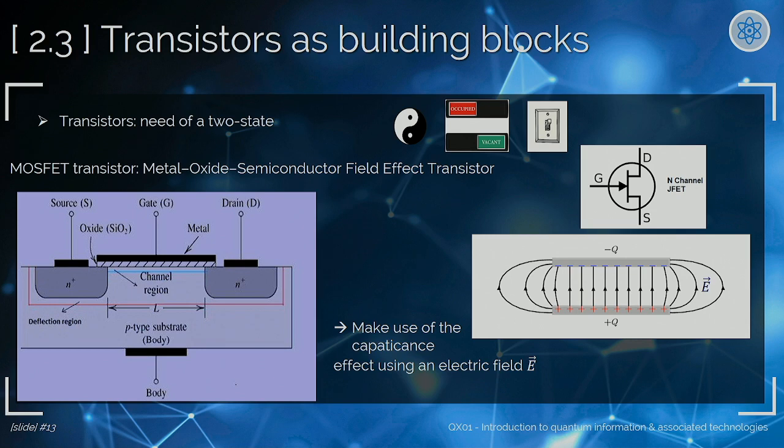So you have a purely capacitance effect, in the sense that you have charges moving up to here, but no current in that direction. But you do have current in this direction, because after some time you will create a channel where the charges accumulate, and now a current flow will be possible between the source and the drain. This happens really locally, under the insulating layer.